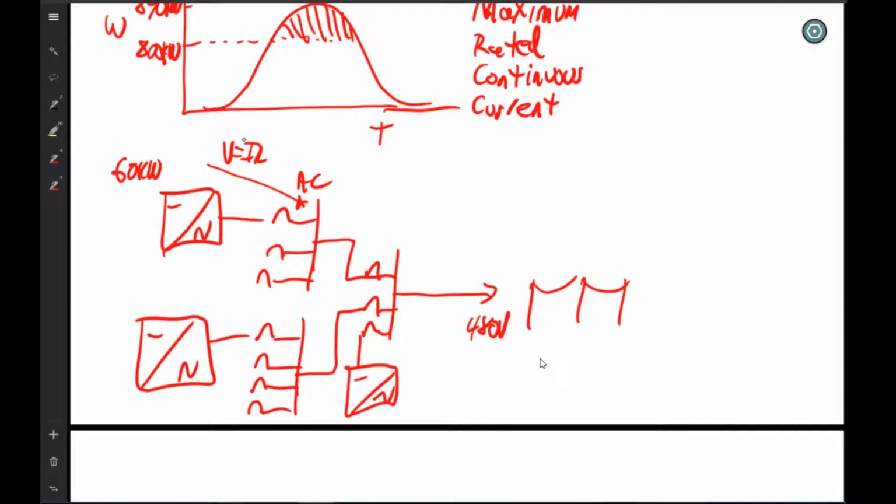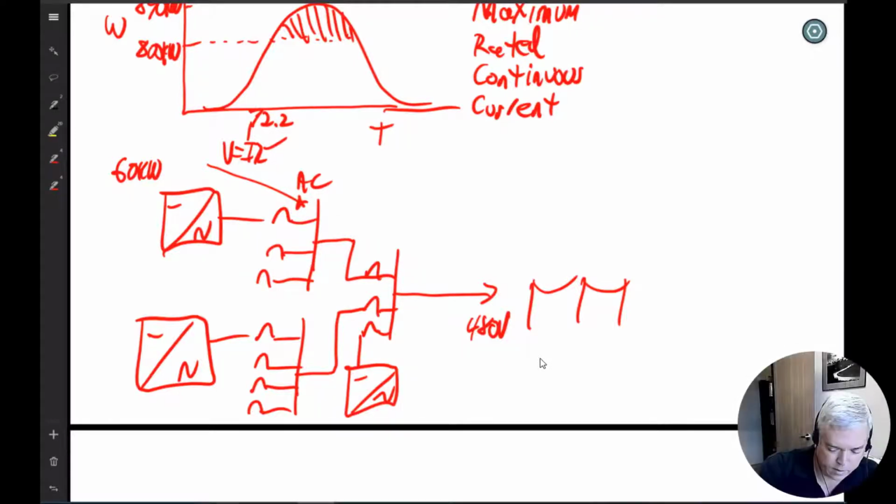So the current is an assumed 72.2 amps. And where do you get resistance from in an electrical system like this? The wire size. The conductor that we size it to has a certain resistance per foot, and it goes a certain length, and you calculate that out, resistance, and that gets you a volts dropped.